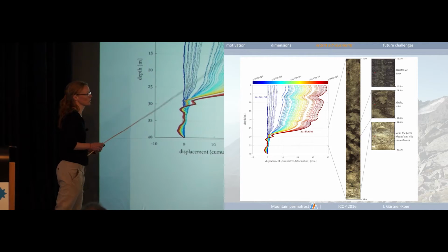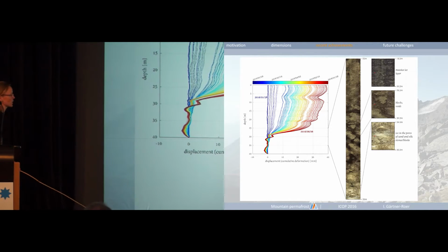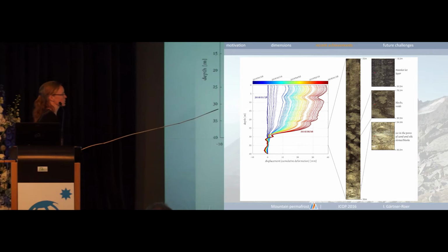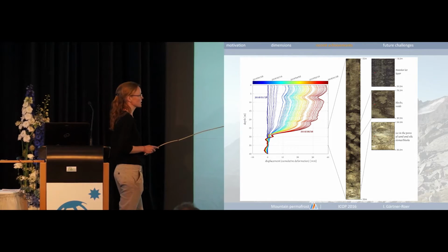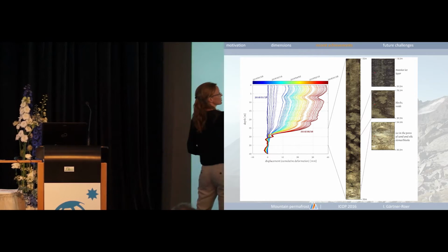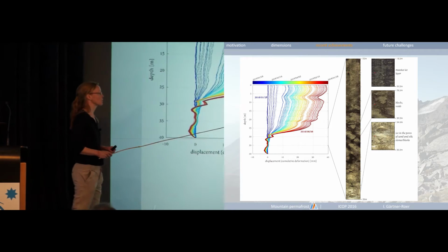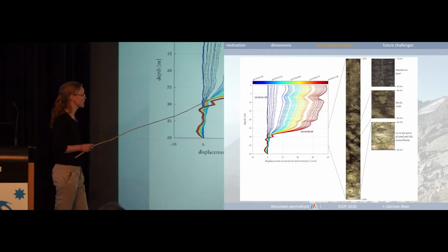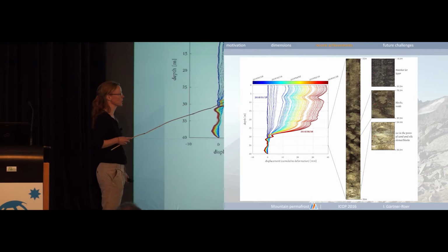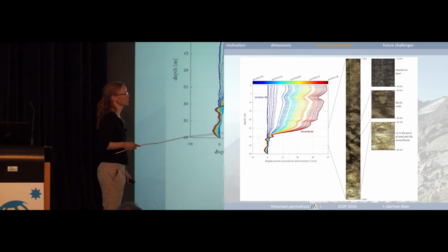And this is also now the very first data we can show you. So we have, it started with the filling in the sand in the borehole in January, and up to now, up to 1st of June, this is a wrong date here, we could measure nearly 4 centimeters of movement. Main part of the movement is occurring here in the shear horizon, as you can nicely see.